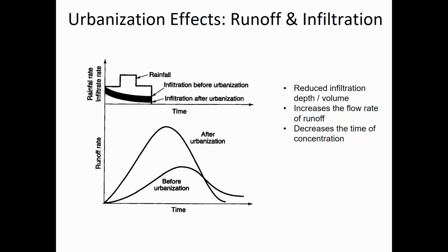Okay, so conceptually what this means is that before urbanization we had lots of infiltration for the same amount of rainfall, assuming that stays constant. If you had more infiltration back in the olden days before we paved over everything, then that meant during those olden days there wasn't as much rainfall excess as there is now. So developments like, you know, that Amazon customer service center, that used to be natural land. You put a big warehouse and loads of parking up on that hill, then the people downstream of that hill are going to see more flooding than they used to.